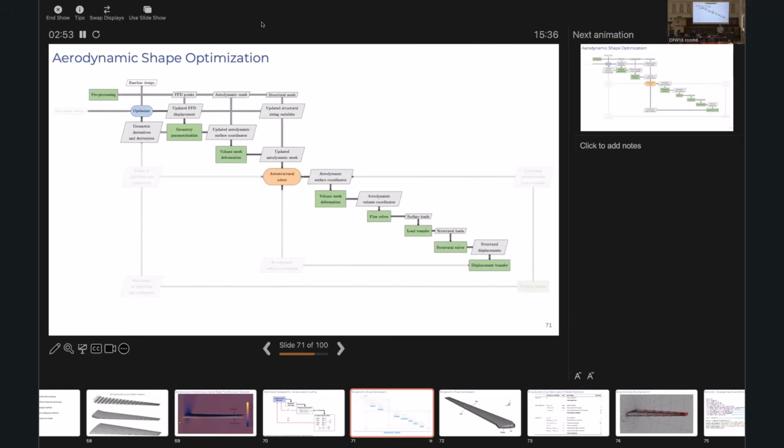So this deflects that wing upwards. So we go back to the beginning of our aerostructural coupling and recompute this again, and we go through this loop, deflecting the wing and solving the aerodynamic flow, and then subsequently the structural solution repeatedly until those two simulations agree. Once they agree, we have our converged aerostructural state variables.